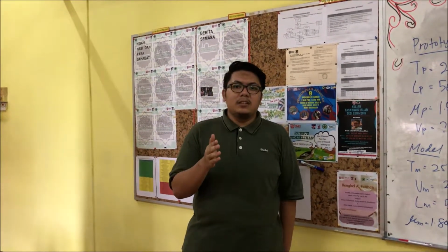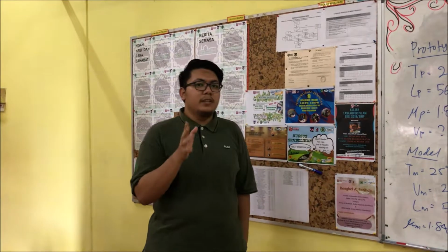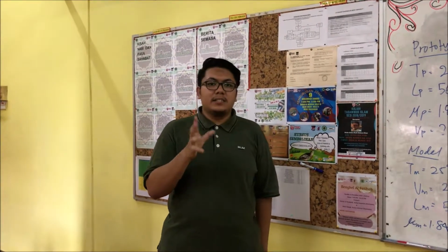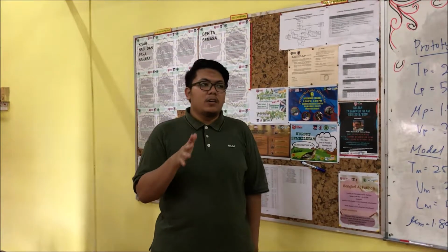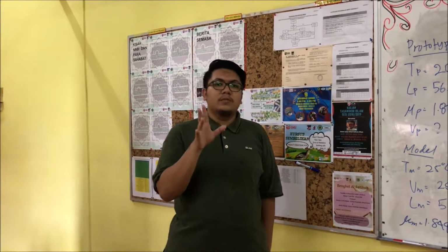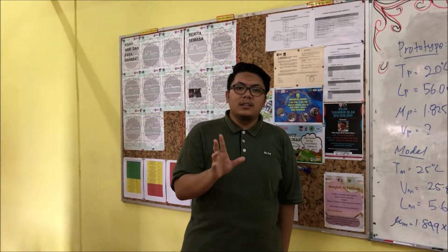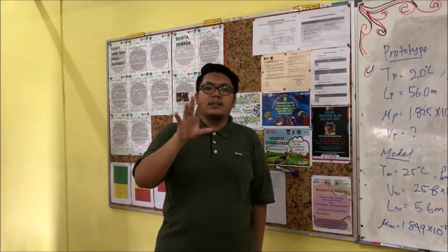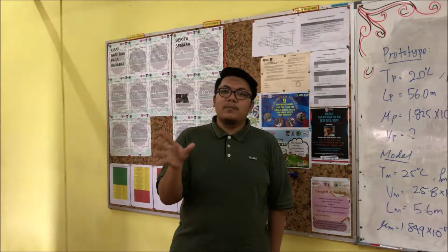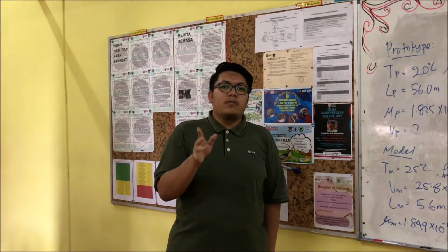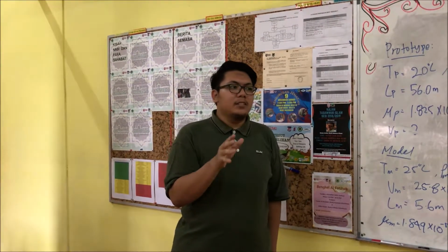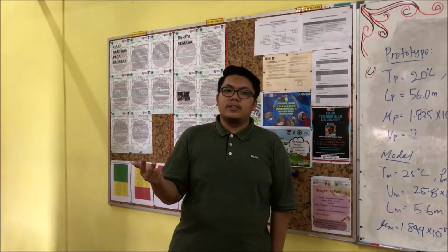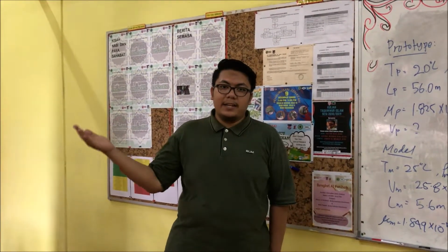Okay, firstly, what is dimensional analysis? The purpose of dimensional analysis is to generate a non-dimensional parameter to help in design of experiment. Okay, it is also to obtain scaling laws so that the prototype performance can be predicted from the model performance, such as the lift, the drag coefficient, the drag force, and something like that.